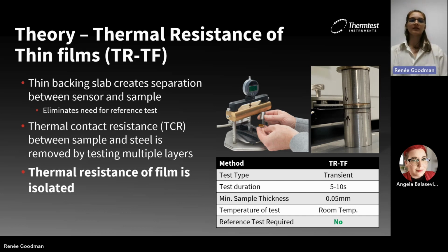So one of the key differences here is the inclusion of this thin steel slab. And what this does is it decouples our sample from the sensor and essentially eliminates the need for a reference test because we no longer have a thermal contact directly between the sensor and our sample.